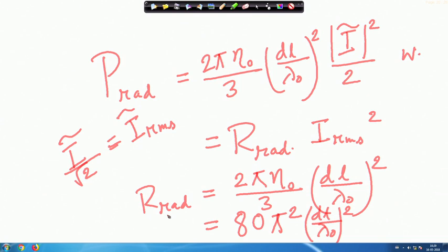In the case of an antenna, power is radiated. So, radiation resistance is a fictitious resistance that dissipates the same amount of power as that radiated by the Hertzian dipole or any antenna when both carry the same value of RMS current. So, more R rad is better.